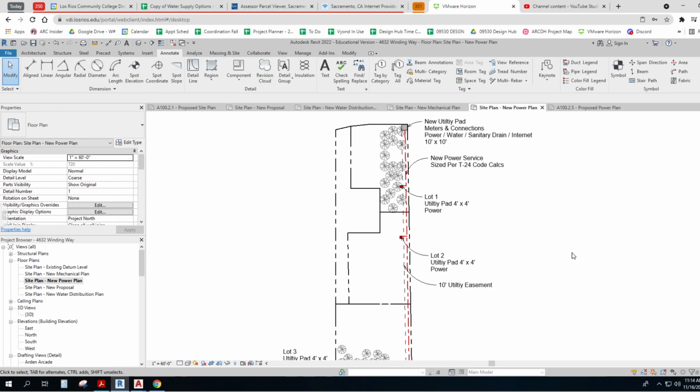They need to really be down deep, and they need to be compacted properly. And there's usually a zone where the sanitary is the lowest, at -8 feet to -6 feet. And then you've got your cold water from -6 to -4, and then you've got your gas from -4 to -2, and then you've got your power. So there's ways that you run it.